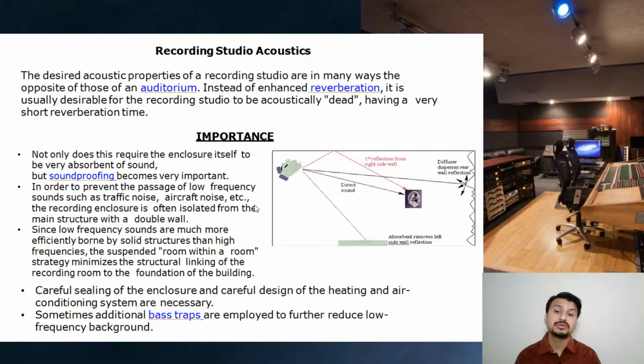Since low frequency sounds are much more efficiently borne by solid structure than high frequency, the suspended room within a room strategy minimizes structural linking of the recording room to the foundation of the building. Careful sealing of the enclosure and careful design of the heating and air conditioning system are necessary.